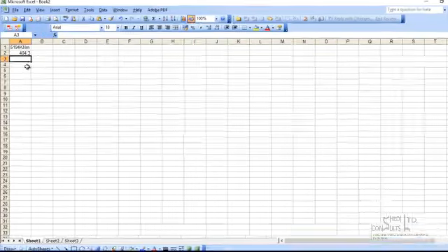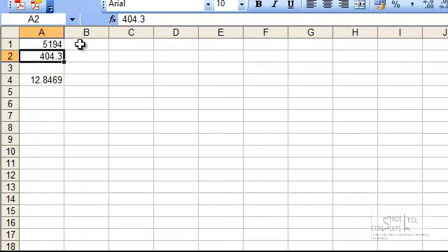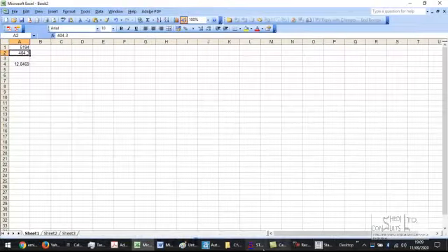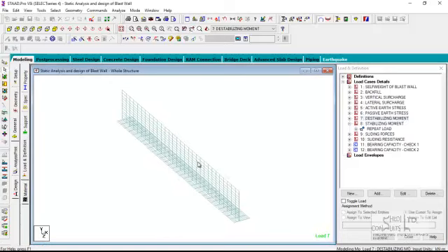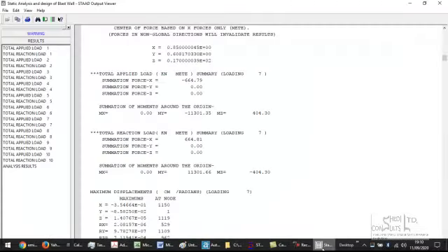So you can get the factor of safety against overturning by getting the ratio between these two expressions. You can see it's far more than 10. The factor of safety against overturning is about 12. So it's very, very satisfactory. The structure is very satisfactory against overturning. One of the contributory factors is the weight of the structure, which is crucial. The weight of the structure is quite significant and prevents overturning forces from being significant.